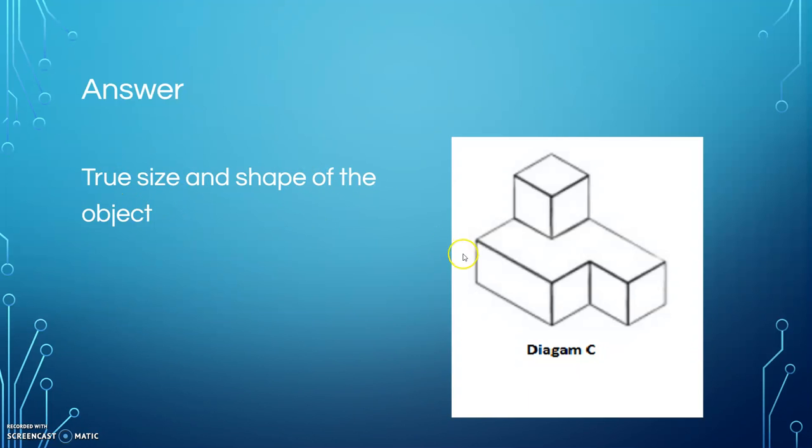And so what this means is that when this is drawn, each side or each edge is exactly the same. So if this is 1 inch right over here, this would also be 1 inch, as well as this and this. On a perspective drawing, which is different than an isometric, images or edges that are farther away are drawn smaller. They use vanishing points, but an isometric drawing does not use vanishing points. It shows the true size and shape of the object as if we were going to make it in real life.